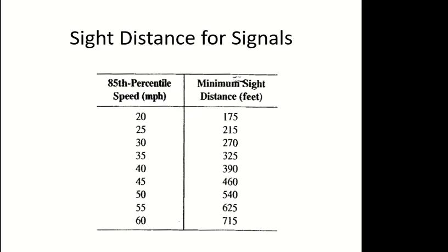The difference between this sight distance and any other type of sight distance is the position of the signal. The signal could be on the side of the road, or on top of the road, but normally it is more prominent because it is at a greater height than a normal car or even a truck, because we want the driver to see it from afar.